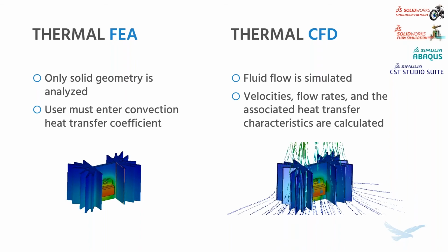If convection isn't a large part of the heat transfer, then this can be very accurate. But if you do have a lot of airflow, whether it's natural convection or you've got a big fan pointing at something, then you really do want to turn to a thermal CFD solution. And the thermal CFD solution is, strictly speaking, multiphysics. Even though we can do this all within one tool in SOLIDWORKS Flow Simulation, we are looking at heat transfer and fluid flow at the same time. You may have heard the term conjugate heat transfer. It's referring to having those multiple types of heat transfer analyzed at the same time.